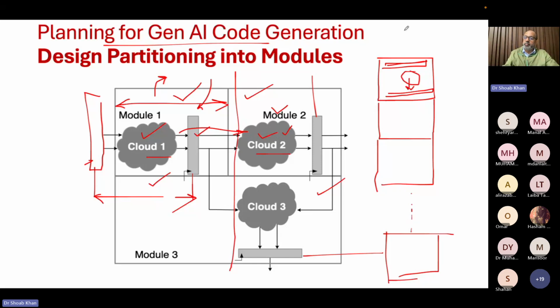Why would you ever do this? Because you say, once it is done with processing a block, I pass the value to this series of registers, and now automatically the output is always saved in the A, B, C, D, E, F, G, H registers. So you unroll the entire number of iterations of SHA-256, whereas one iteration takes a 32-bit value, and there are 64 of these values. So you have 64 of these processing elements, and you design it once, and then you place them 64 times.